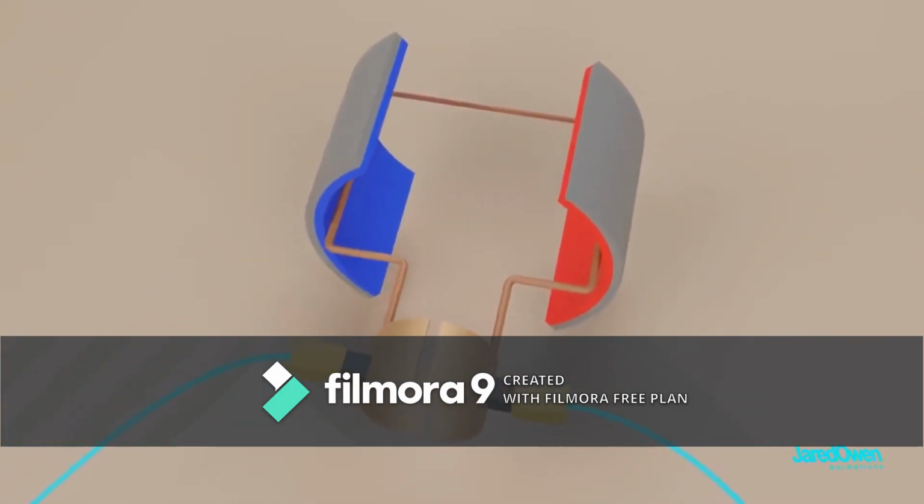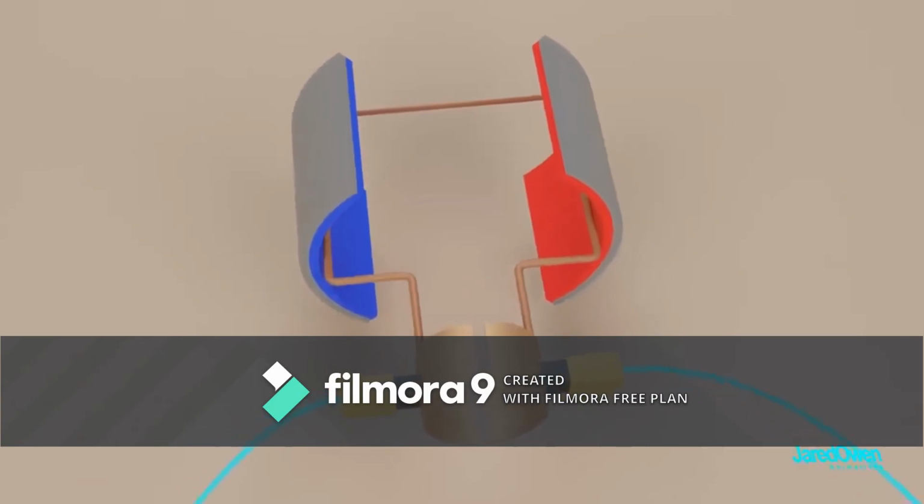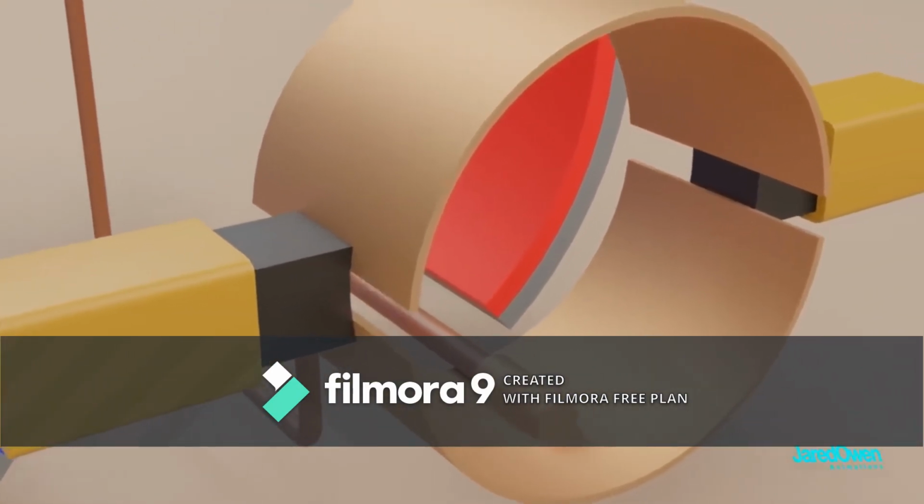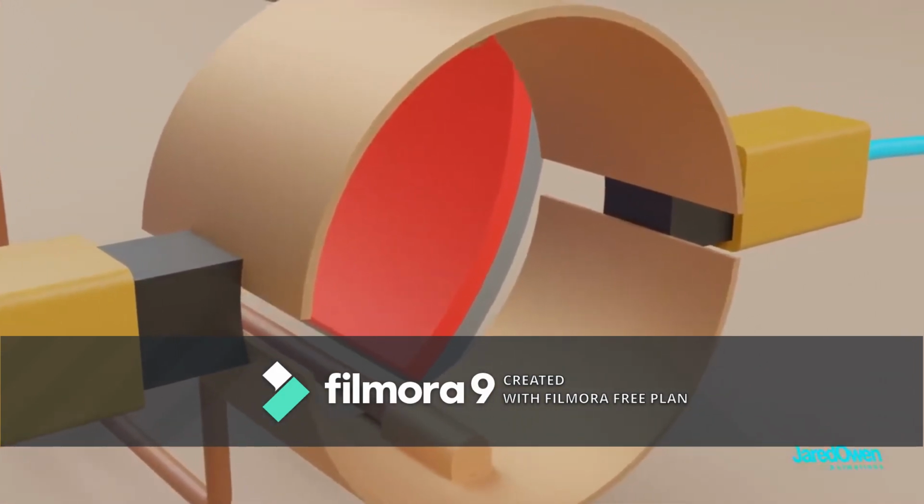Now so far we've only used one loop on the armature. This will cause our motor to have an irregular speed, and in fact, we could get stuck in this position, with the brushes halfway between commutator segments.